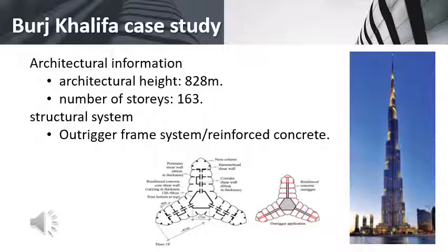The hexagonal central core consists of reinforced concrete shear walls with thickness between 130 cm at the bottom to 50 cm at the top. This combination was developed to overcome the lateral loads. Wind force was dominant in the lateral loads. The maximum lateral drift at the top of the building was 1.2 meters. So a model at 1 to 500 scale was tested using wind tunnels, which led to the development of wings on the building, and at every stage the form of the building was reshaped after repeating these tests, which resulted in a reduction of the wind load to an absolute minimum.